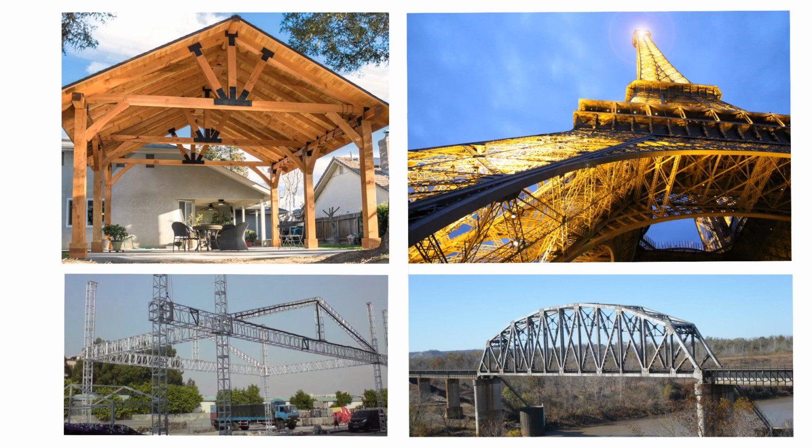And so the trick in these truss systems is really that the bottom chord and the top chord are very far removed from each other. Because if you do that, then you actually have an effective, very long lever arm between those two, right? So you have tension on the bottom and compression on the top, and everything in between just provides space. So that is kind of the idea behind a truss.